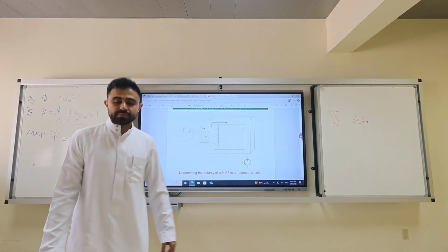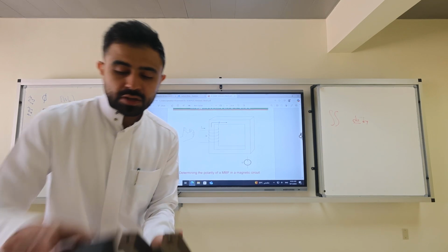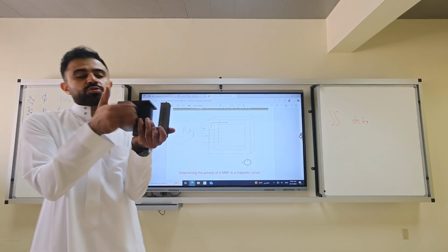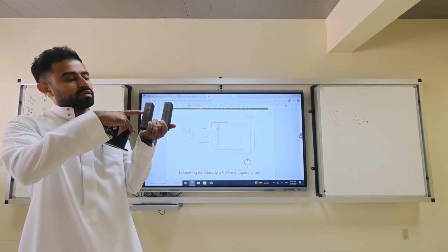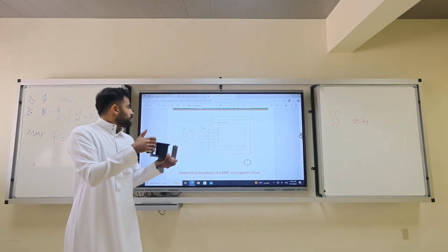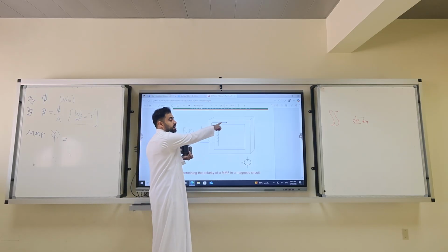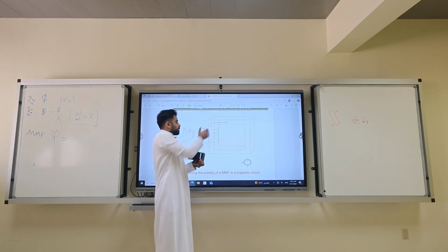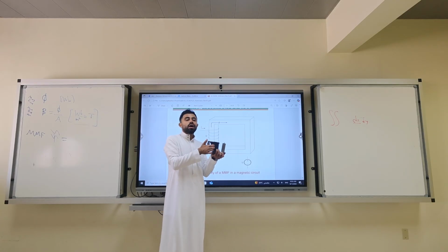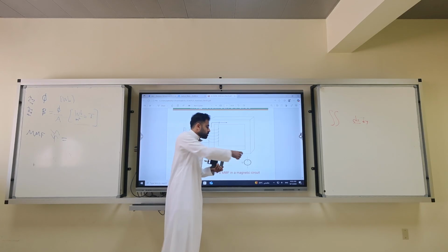What's the polarity? If we put this, we put that, it goes this way. Where is the plus sign? Well, it's here on the top. Why? Because it's where the flux starts flowing. So the flux starts flowing here, right-hand rule. So you have to use right-hand rule every time you put the voltage source.